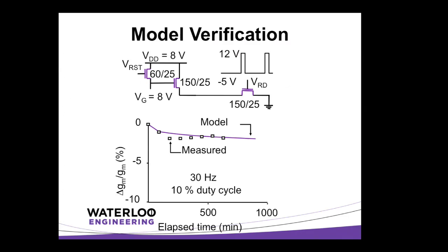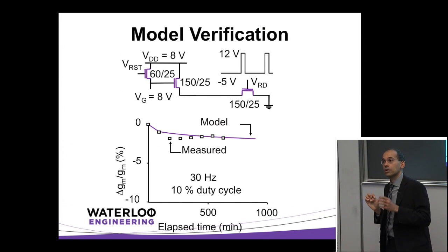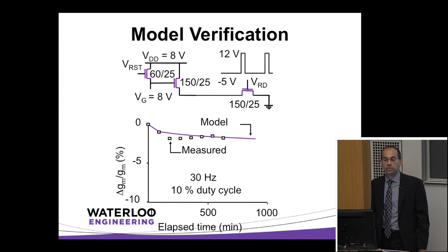Anyway, we came up with some models to determine it. The saving grace for medical, and this is actually better than in the display field, is that the duty cycles in the medical application are a lot smaller than the duty cycles in displays. For example, if you talk about a megapixel array for a camera, you're only really turning on a row of transistors once every, say, 1,000 or 4,000 times. So your duty cycle is like 0.1% or like 0.025% or something like that. It's tiny, okay? Because the duty cycle is small, the impact of the VT shift is not so bad.